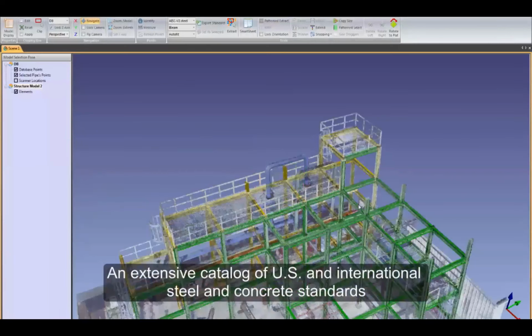Okay, this is a good question. Thanks for asking it. You need to know that laser scan technology cannot penetrate underground. Laser scan can only scan and survey what we can see with the naked eye. Everything that is buried underground, or, for example, steel rebars in a concrete element, unfortunately, we cannot use laser scan technology.